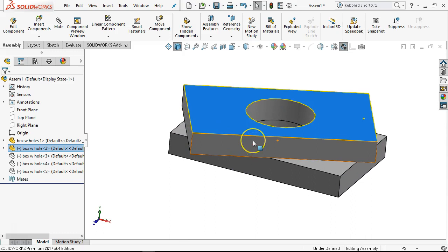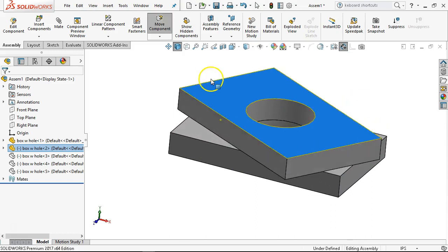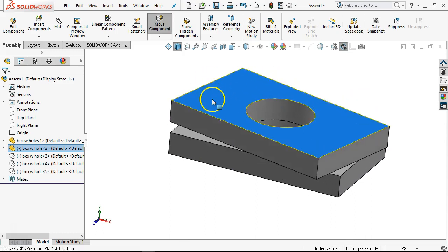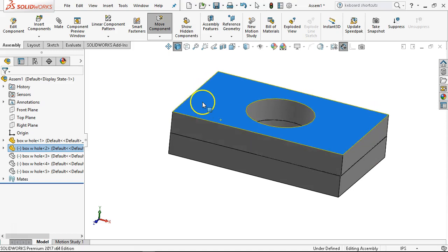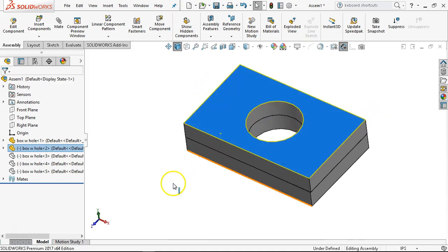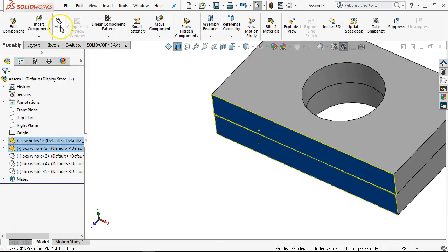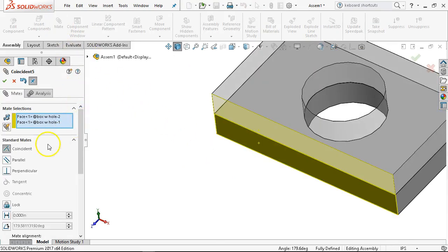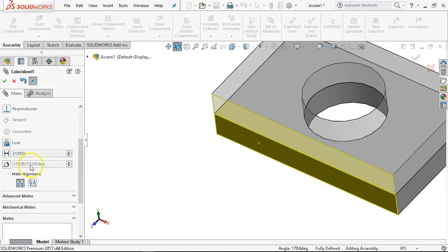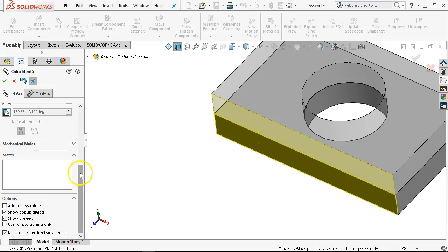If I want this instead to be limited, now in this case it'd be a limit angle because of the rotation, then I would want to look at that geometry as, let's go face to face, and we'll go into the mate. Anything that goes beyond setting a hard number for the angle, you're going to jump over to the next tab, Advanced Mates.